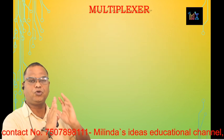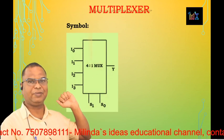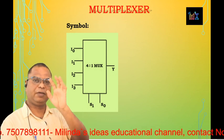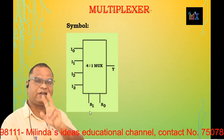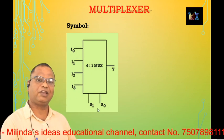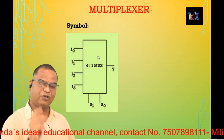Now in front of you, the symbol of that 4:1 mux is going to be displayed. As there are 4 inputs, I0, I1, I2, I3, as we mentioned, 2 control lines, 2 select lines are required. The 2 select lines displayed are S1 and S0, and Y is the output, and it is a 4:1 mux.